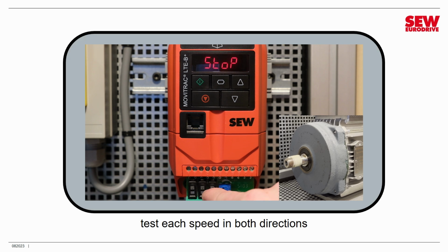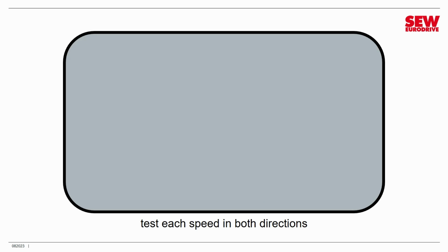We'll try counterclockwise, do the same thing, but we'll put our switches both back to 0 first. Counterclockwise, minus 100, minus 250. All right, we're going to turn the pot all the way up again to create a 1 bit. Gives us 500. And finally, we go up to 1000, both bits on. So counterclockwise works. Let's stop it, and let's try one final thing. Let's start it up again and do a rapid stop by turning both on at the same time. And boom, you can see it stops a lot quicker, just like what we expect.